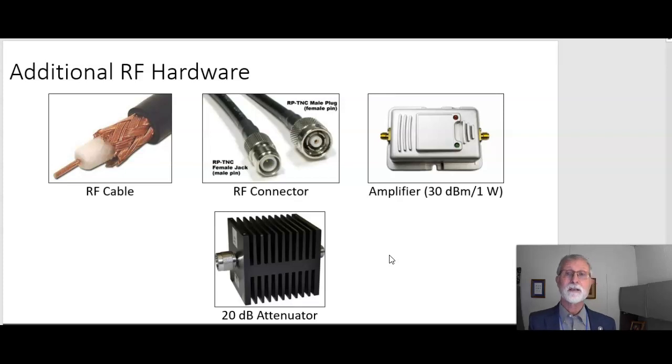How is it going to be connected? What type is the connector? I think one of the items on the specification sheet showed you the connector type. That connector type then helps you choose that antenna. So if you're already in an existing network and say, hey, we're running cable and it's only going to be RP-TNC connector. Okay, so that means you've reduced the number of potential antennas, only because somebody's chosen for you already how it's going to be connected. So a lot of those just come into play.